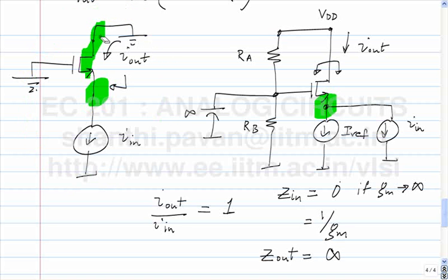So in this amplifier, we see that the gate is grounded and the gate terminal is common to both the input circuit and the output circuit. Here you also see that the drain is grounded, but that's beside the point. What is usually done in practice is to put a load resistance here and convert this current into a voltage.